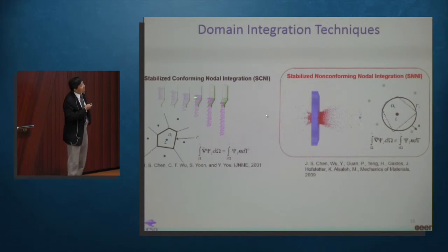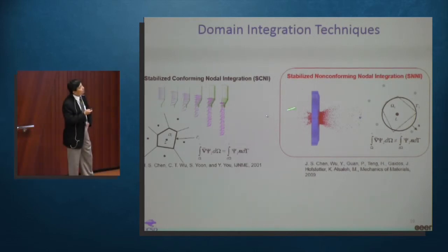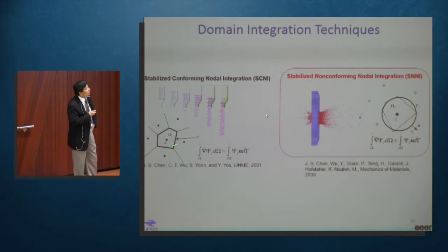Of course, this kind of approach is fine for very large deformation problems like metal forming and things like that. But again, when I have to move away from pure Lagrangian and go to a so-called semi-Lagrangian, where the kernel moves with a material point but not necessarily covers the same set of material points, then I don't want to reconstruct this kind of Voronoi cell, conforming cell at every time step. So you have to sacrifice somehow. You have to relax this condition.